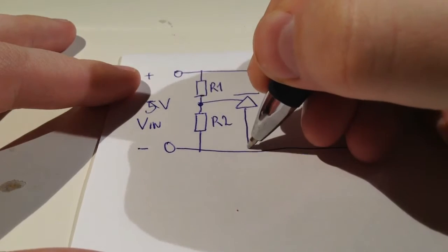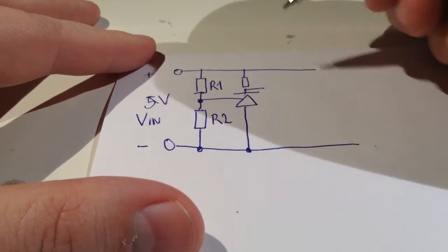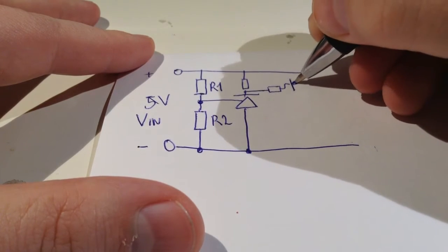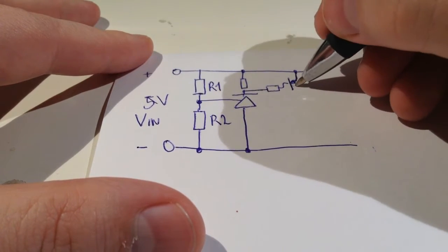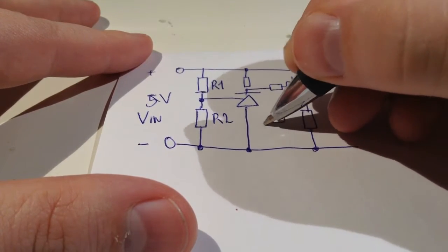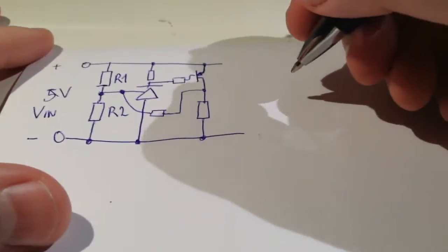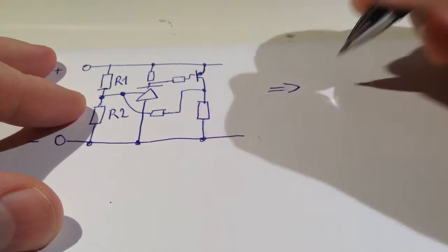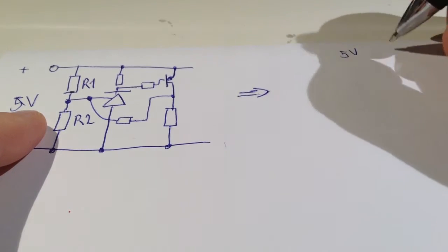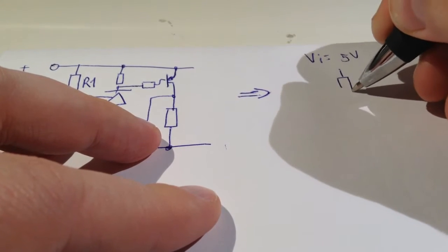Okay, so here is basically the circuit that we have now. The Commodore saver, so you have 5 volt on the input. It's the power supply input, or the input that takes the power supply connection. And whenever that 5 volt goes over the threshold, then the TL431 will trigger. The problem with that is it doesn't go all the way down to 0 volts, so we have a second transistor there, a P-channel transistor, that helps it trigger all the way.